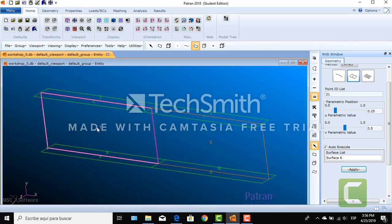Now we have to create 2 other points, but at a different distance. As I mentioned, we're just going to change the top one to 0.75. The bottom one stays the same. On the surface list, we're going to click on the first surface and on surface number 6. Since it's in auto execute, it just created 4 points that are going to be critical for us and simplify, in a way, our job of creating some circles.